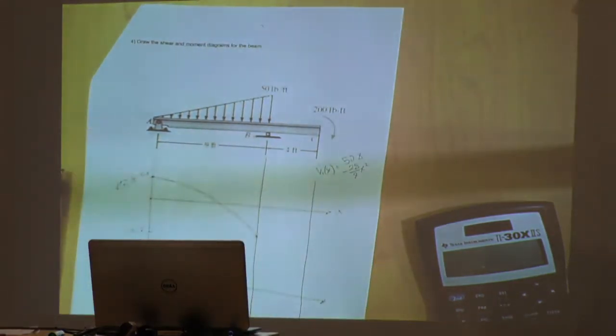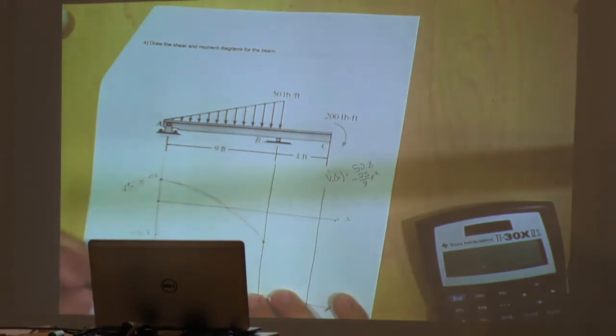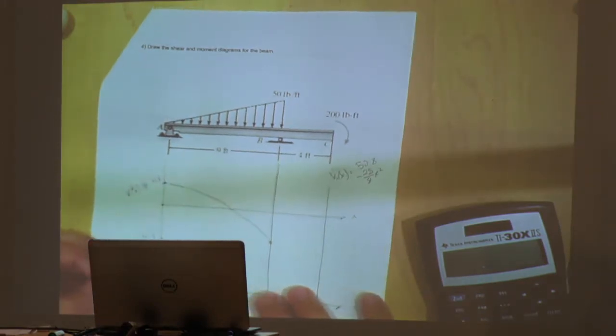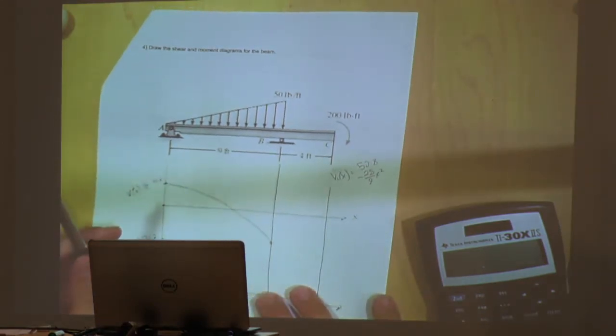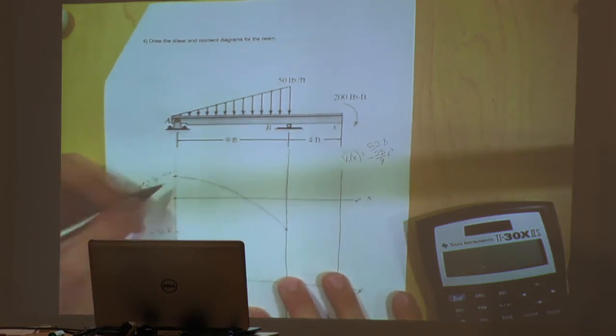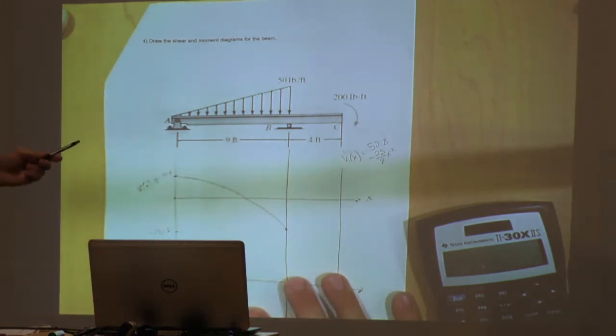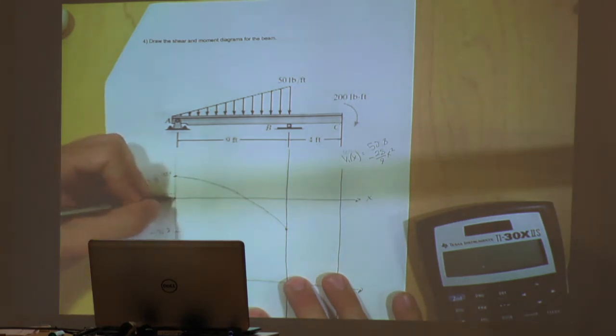So what's key about this graph? Is there anything particular about it? Are we done with this shear? No, that 172.2 is equal to By, so it's going to bring us up to 0. If we look at our end conditions, at 0 we have our Ay, which, if we remember from the board, is 52.8. So starting at 0, it brings us up to our initial location.